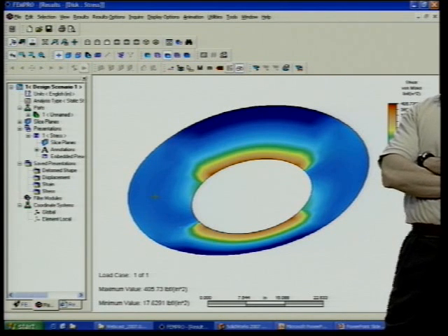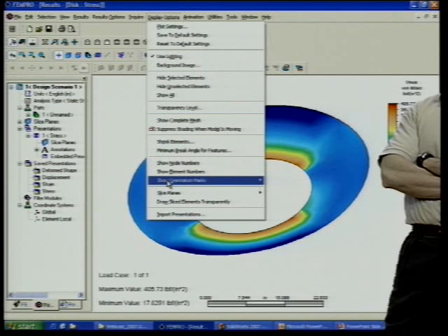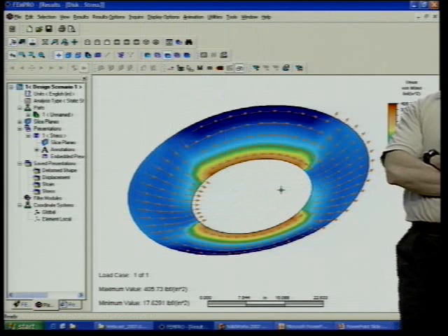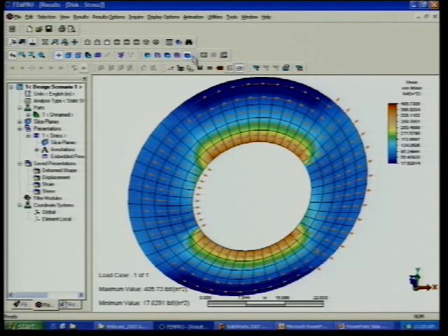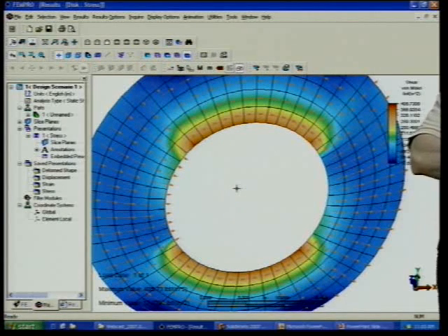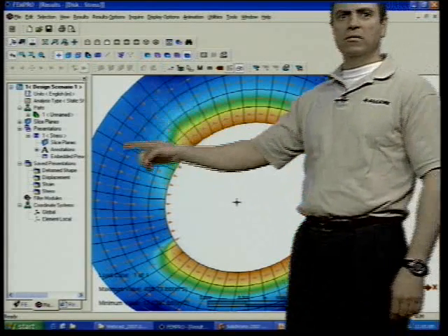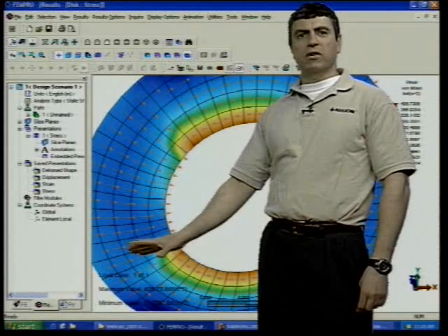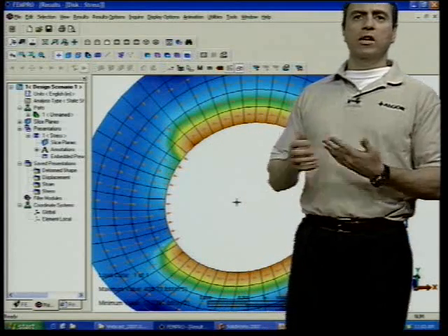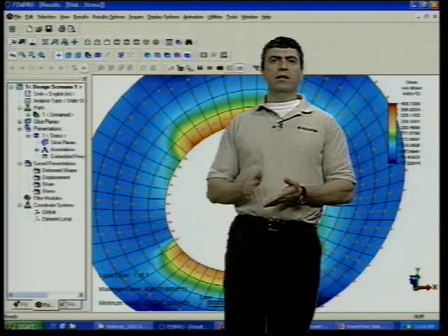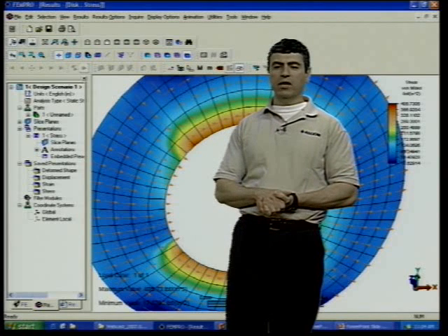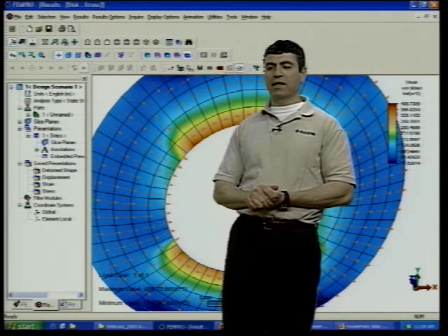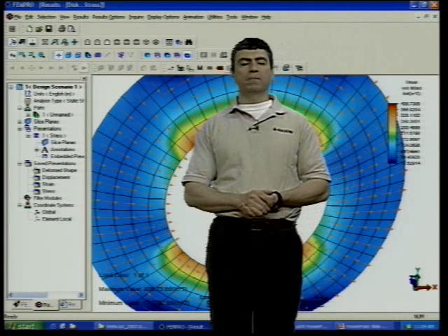And again, if you go to display options and show these axes here, and maybe show the mesh and zoom in, you'll see how they are all uniform. They're pointing all uniformly around the mesh. That's because it's a very structured mesh. So you have to be aware what your mesh looks like to be able to orient the lamina appropriately, to know which selection, which orientation method you should use for your laminate axis X, Y, and Z.